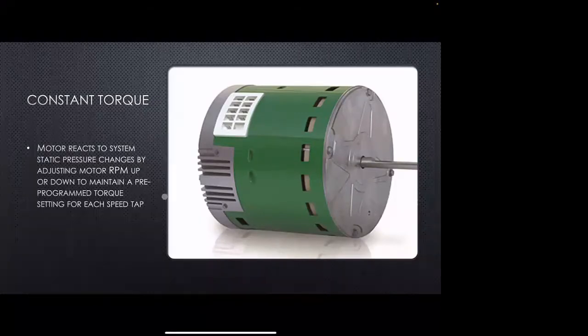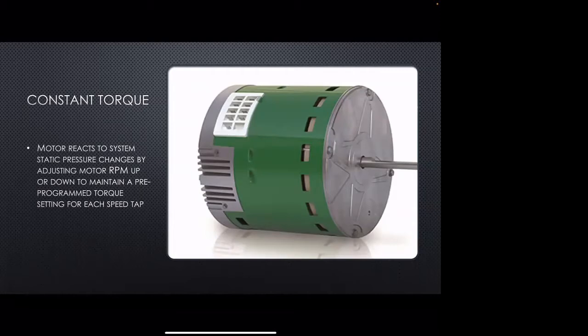On air handler systems. On air handlers, yeah, that's the very, very big one that we see them on. The FV, the Frank Victor model numbers of our Carrier Bryants. That's where you'll see these here. And this is where you get to select your speed tap. These are also like an X13 style motor too, that you may see out there.